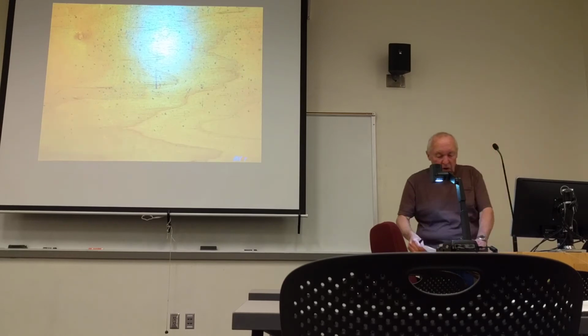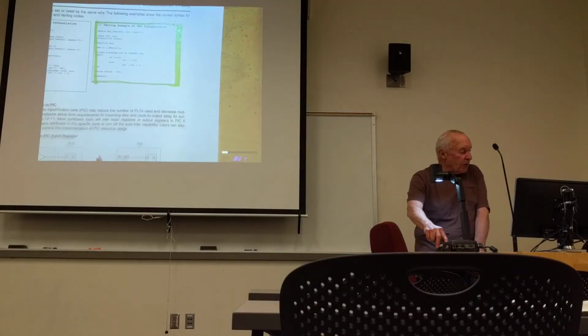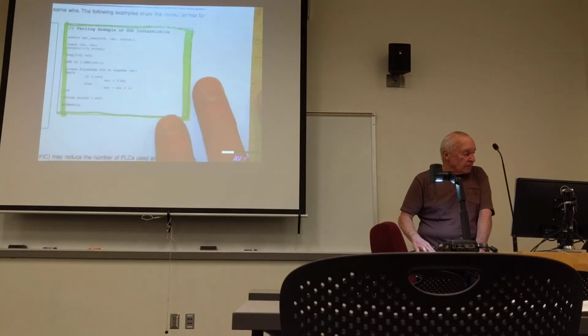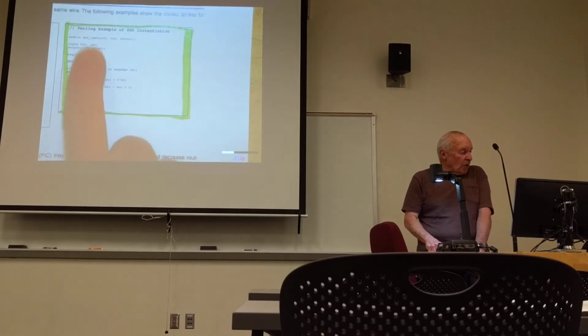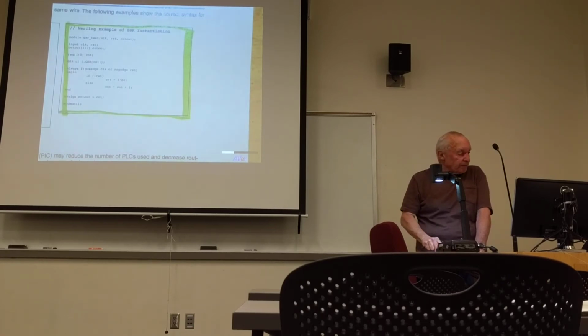We talked about that global set reset function. This shows you the code on how you can do this. Here I want RST to be my reset signal that goes throughout the FPGA to initialize different circuitry. That's how you instantiate it.